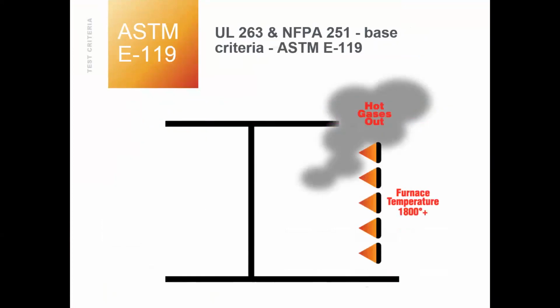Where you're never going to see this fabric product, ever, is ASTM E119 rated applications, and I'll tell you why. So we just talked about UL 10B, right? It's an opening protective fire test. ASTM E119 is that test, except it's for walls, not for opening protectives. It's the same 1800-degree furnace, the same rigmarole that I've already been discussing, but it's a wall in that application.